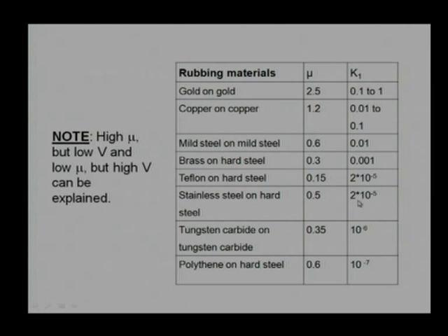Quite possibly the material combination which we are using has some sort of inclusions, some sort of manufacturing defects. If there are voids, cracks will form a fracture surface, or a surface which can be easily fractured or delaminated from the material, even though they can show low coefficient of friction.